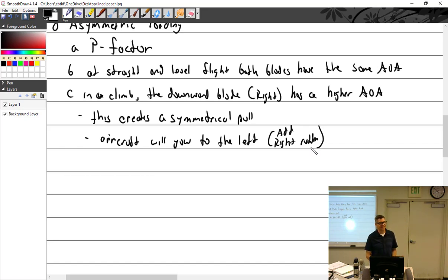Is this similar to adverse yaw, or is that more of a torque thing? No, adverse yaw is completely different. Adverse yaw is when you're in a turn and you drop the right aileron, let's say, and you lift up the left to make it turn this way. Because you added lift, and drag is a function of lift, there becomes more drag on this wing that you want to go that way. And so it tends to scoot the plane around kind of funny. So it banks, but yet it twists funny, so you add rudder to bring it back in.